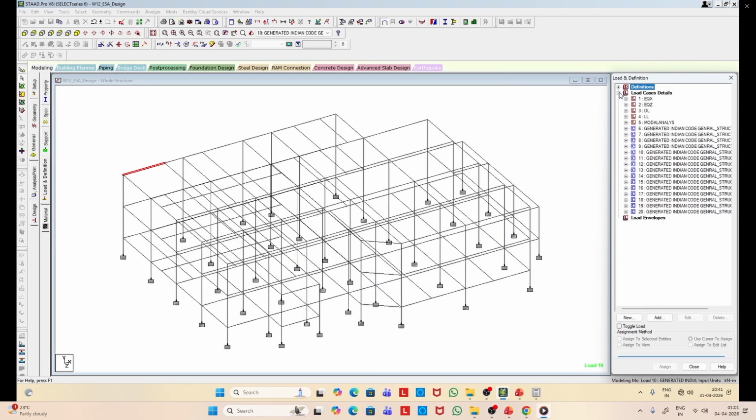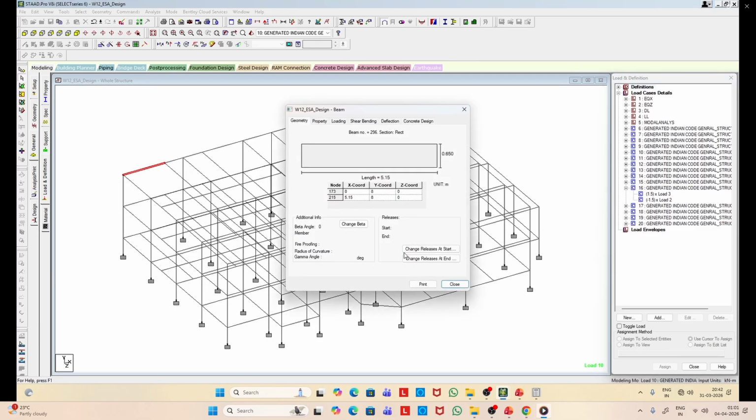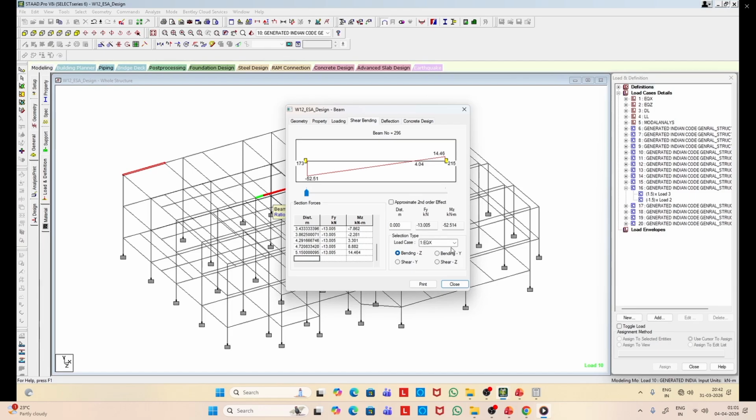So here is the 16 load case, and you can see it is a combination of load 3 and load 2. And you can also notice the load factors. Now, if you select that load case, say 16, so you can see the different values of forces and moments along the distance, and the plot is also shown here.